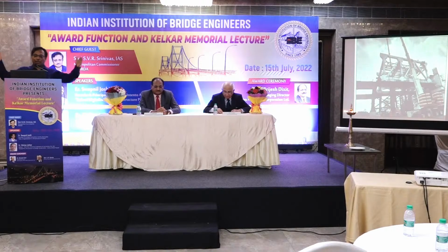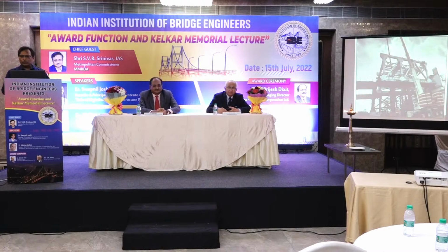It cannot be assembled in one go and pulled across the railway track. So it was assembled in three parts. See, across the railway portion, one middle part was assembled, and then we launched it, taking a block from the railways of more than 5-6 hours, and then the side portions were attached. A lot of apprehension was expressed by experts that it will not match the camber. The whole position was very, very critical there. More than 80,000 friction bolts were used there.